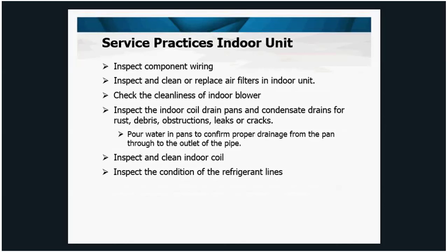But what you really want to do when you inspect refrigerant lines is look for signs of oil. Oil circulates through the system with the refrigerant. If there are leaks, you will see oil residue. Now, where you see the oil is not necessarily where the leak is. There are many cases where you have a leak at a fitting up in an attic and you notice the oil where it comes out at the bottom because it tracks along the pipe. But it's a good indicator that there's a leak, so wherever you see the oil around a fitting, you need to check that fitting for leaks.